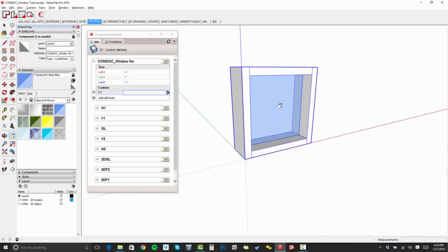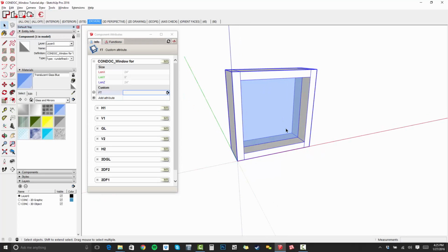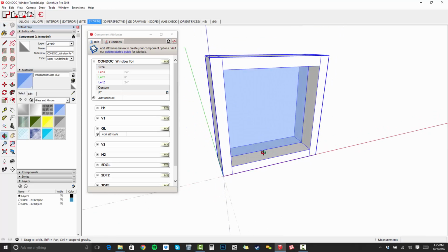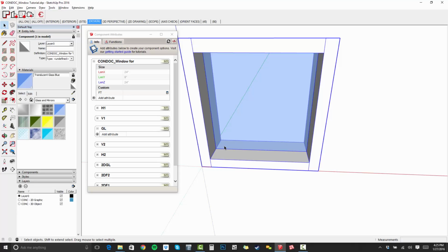That's all good. Now when I'm setting up these formulas, I need to really just look at each piece of this. So they're really all based on either the length X, and really X and Z are the main ones. Glass is going to be based on Y. So like the glass is actually kind of easy. So let's add an attribute to the glass. The glass needs to always sit on the green. It's always going to sit at half of the window depth.